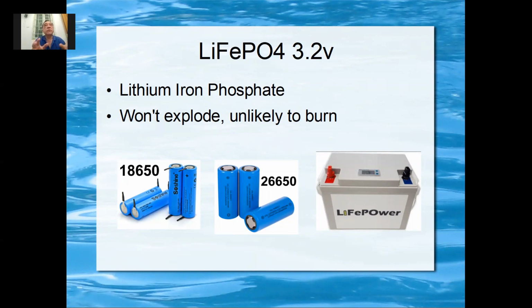And the problem comes with 48 volt. For 12 volt it is 4 cells, 24 volt is 8 cells, 48 volt is 16 cells. But sometimes you put 15 and you still get 48 volt, but if you put 16, it's actually 50, 52 volt like that. So it's actually much more.